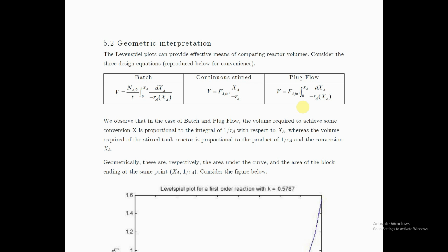And that's virtually impossible to accomplish, right? So in your plug flow case, you are requiring that your wall friction doesn't cause laminar flow, or even if there's perfect turbulence, that turbulence doesn't happen laterally. You are requiring that there's no diffusion, or more generally dispersion. So you can't allow any axial movement, otherwise you don't have plug flow anymore.